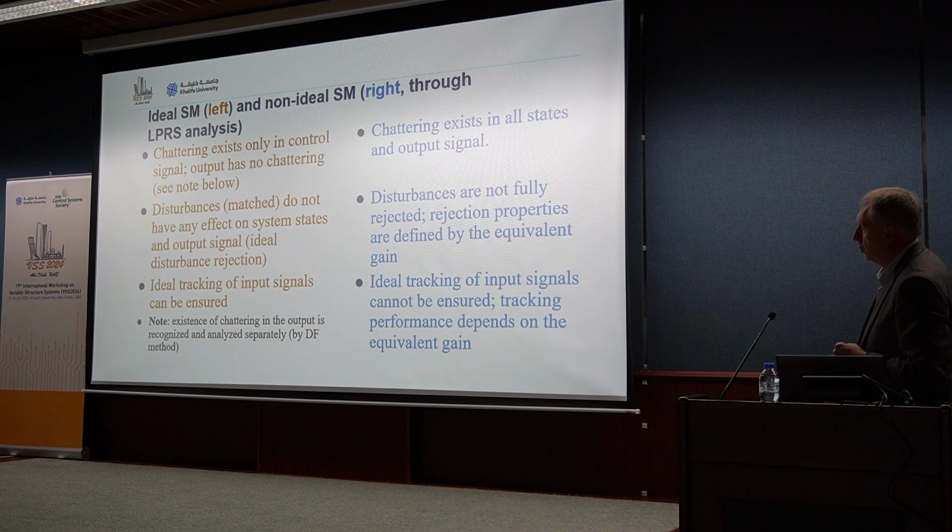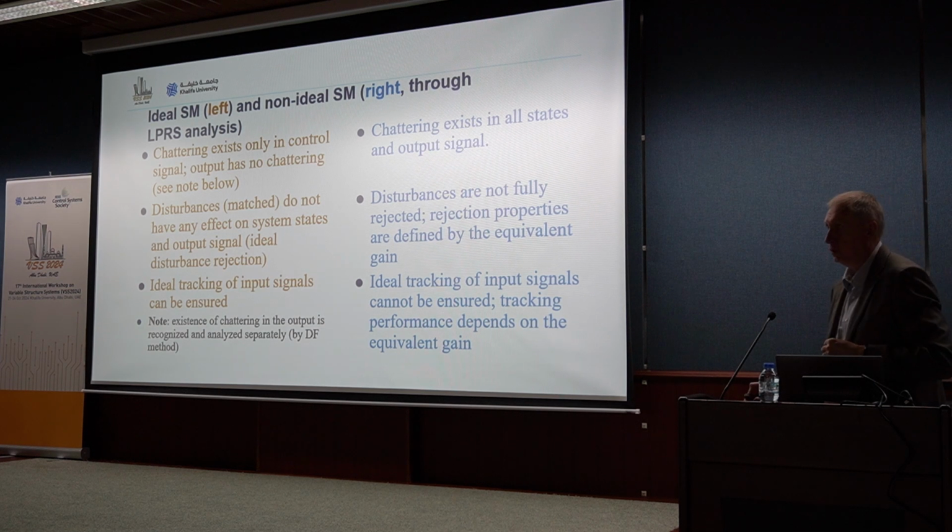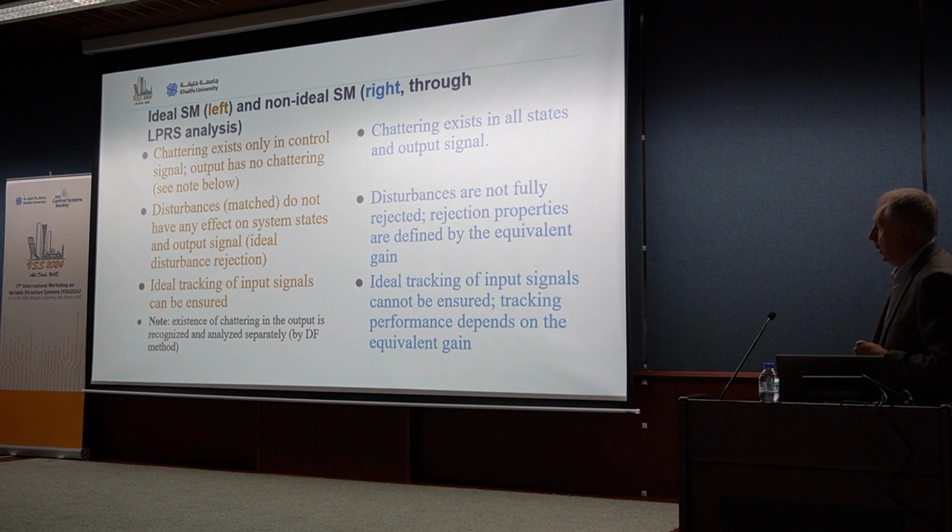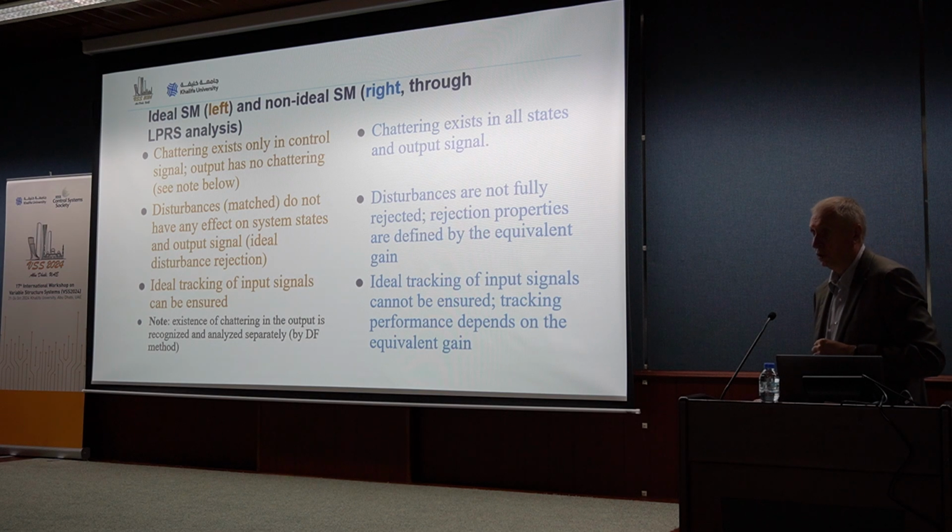In ideal sliding mode, matched disturbances do not have any effect on system states and the output signal. Ideal disturbance rejection. Here we will find that disturbances are not fully rejected. Rejection properties are defined by the equivalent gain. In ideal sliding mode, ideal tracking of the input signal can be ensured. In LPRS analysis, ideal tracking of input signals cannot be ensured. Tracking performance depends on the equivalent gain.